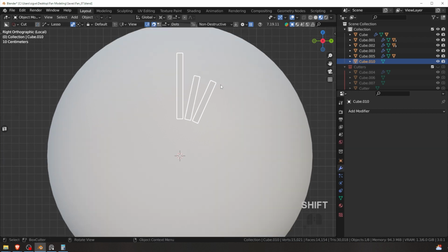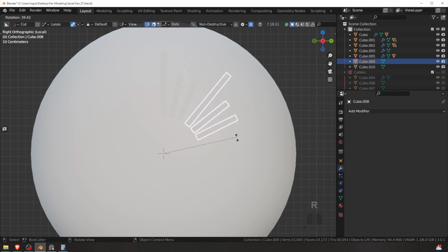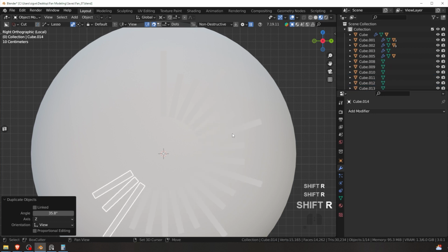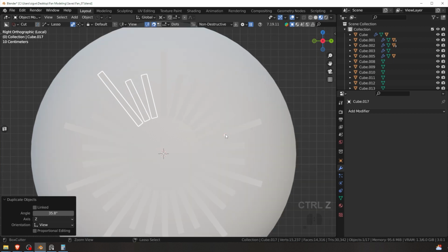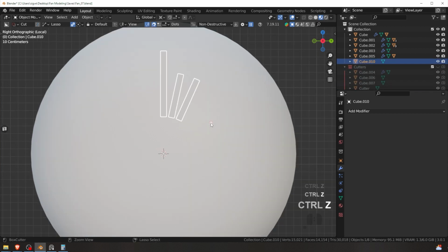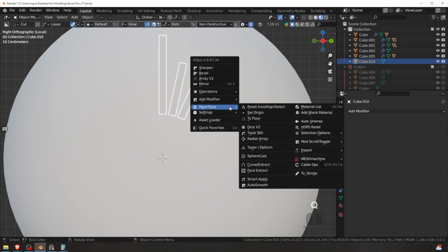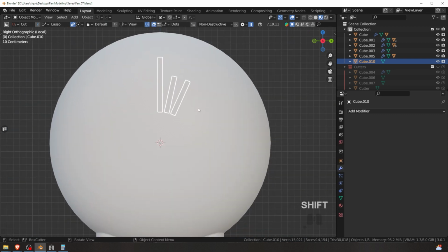If you don't have that, you could do that without add-ons by simply pressing Shift D, then R. That's very important. Don't click anything else, and then kind of eyeballing it, just apply it. And now just keep on pressing Shift R multiple times. Boom, like that. So it's possible to make it this way. Now something was inaccurate right there. I think the distance was kind of messed up. That's why it's way better to just use the add-on. But it's possible. It just requires some fiddling around.